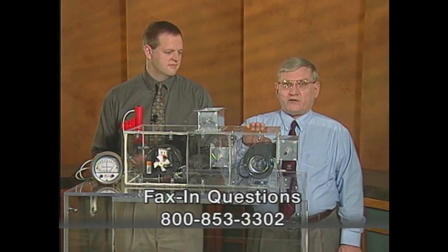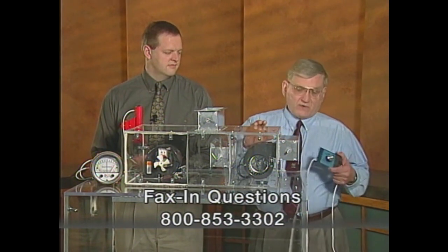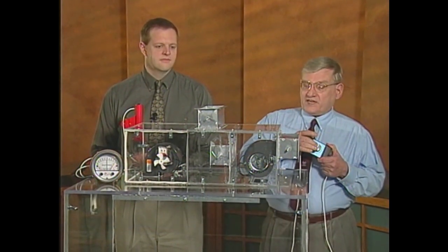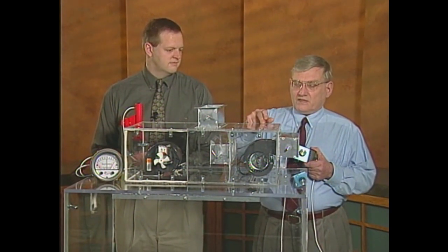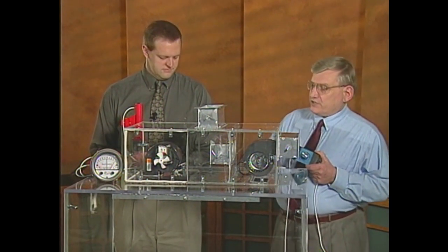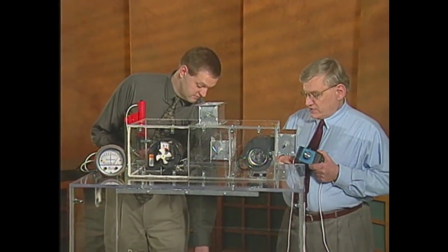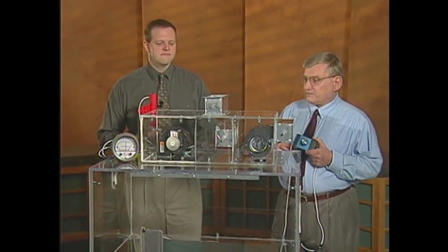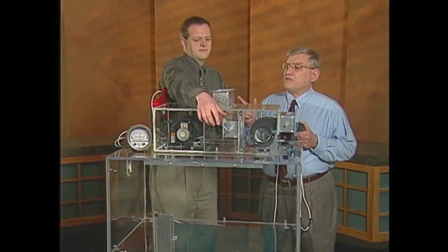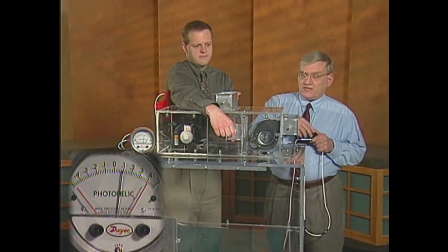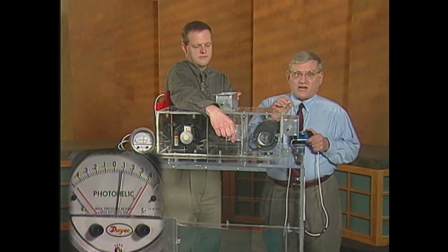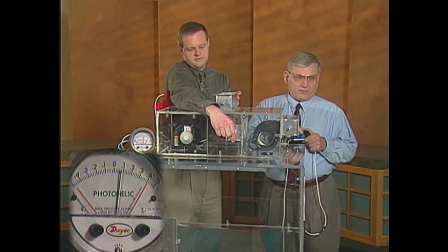Modulating the exhaust will allow you to control space overpressures. And I'm going to do that with basically a fan speed switch we've hooked up to the central exhaust fan. Now, John, for this demonstration, I'll need your help. Let's turn on the outside supply fan. Outside air damper is at minimum outside air. And I'm going to turn on the relief fan so it's operating at the slowest possible speed.